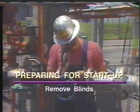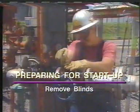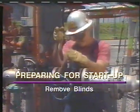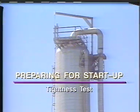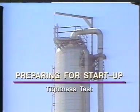All blinds installed during the shutdown process must be removed prior to startup. Before the tower is brought back on stream, it is necessary to perform a tightness test to make sure there are no leaks in the column or in the connecting equipment.